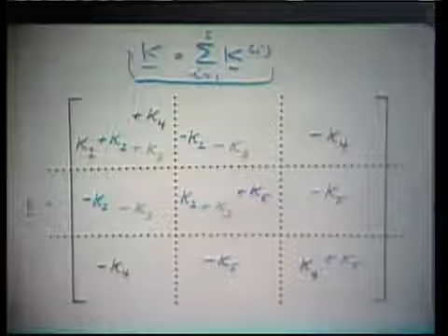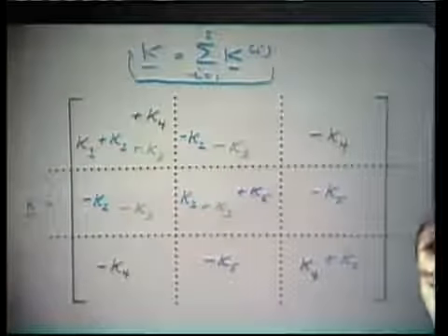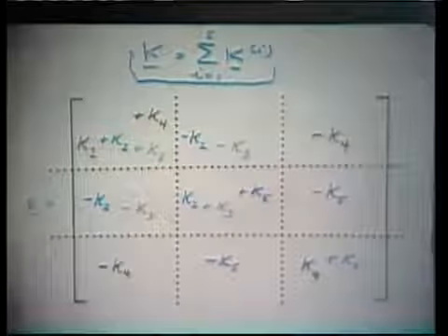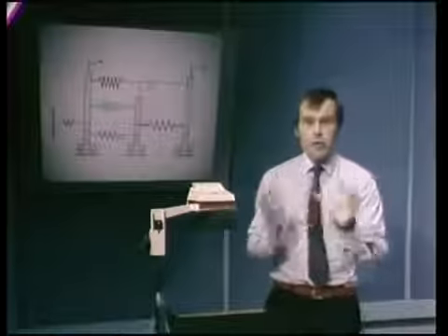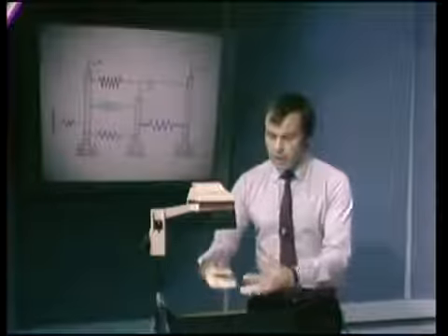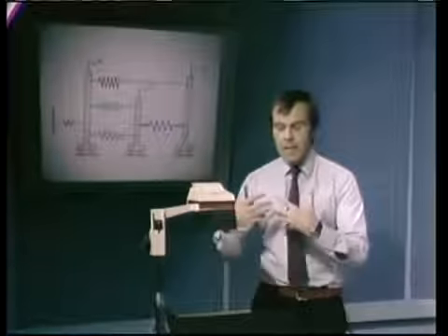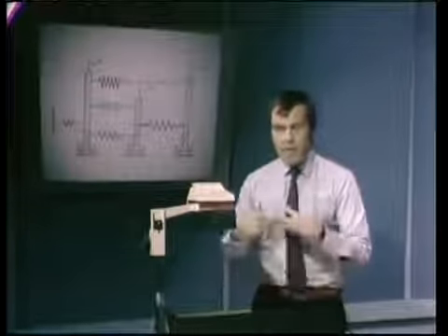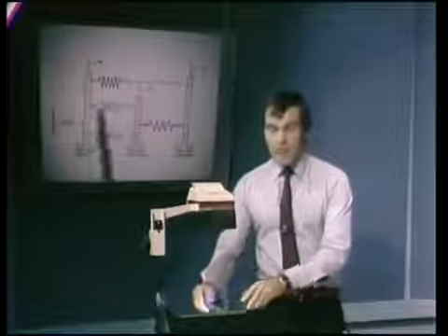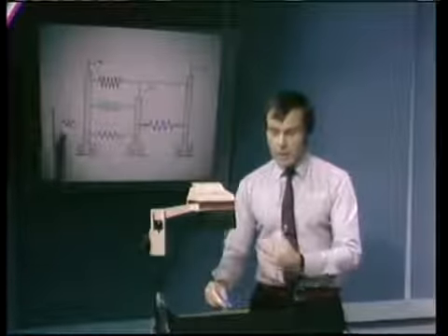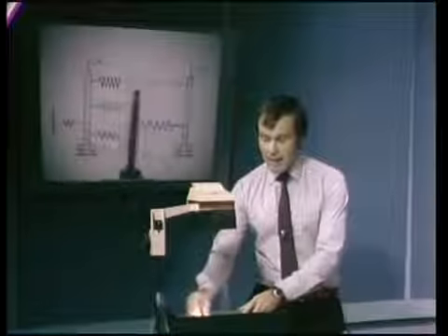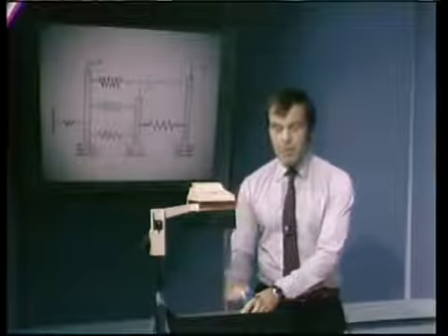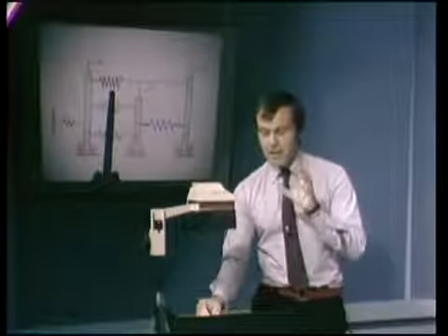and this mathematical process, once again, which we call the direct stiffness method, has a physical analog. You can understand it physically in the way I've shown here. Namely, you're starting off with a blank K matrix, no elements in it at all, and you simply add one element after the other into that K matrix, filling up the K matrix that way. And the additions are carried out, this is important, by taking the element matrices, and adding them into the appropriate columns and rows of the K matrix.